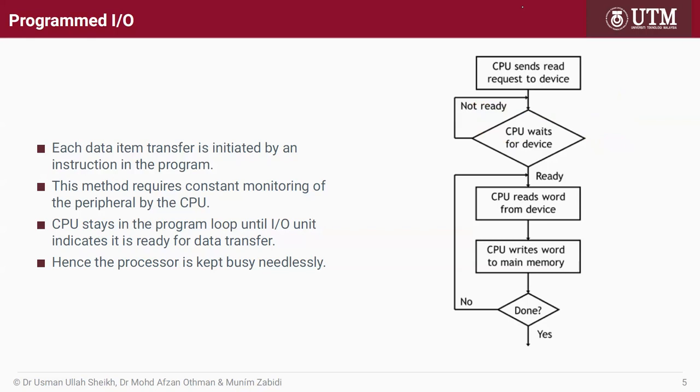So basically, the processor is busy waiting. Okay, it's busy, but it's only waiting, not doing anything. And when the device is ready, the CPU will read from the device, and then the data is sent to memory. Okay, and then the procedure continues. So simple but not efficient.